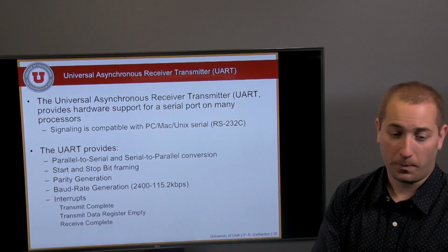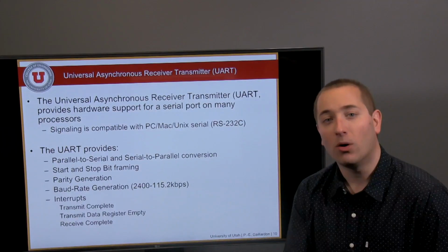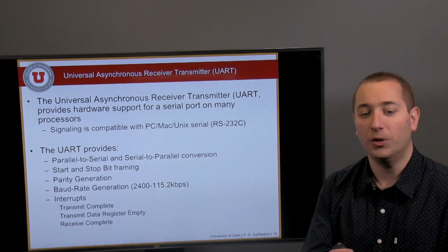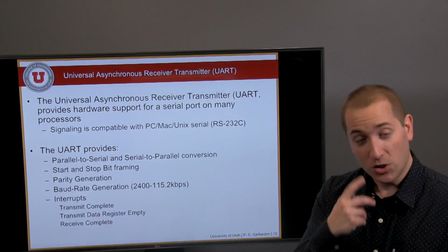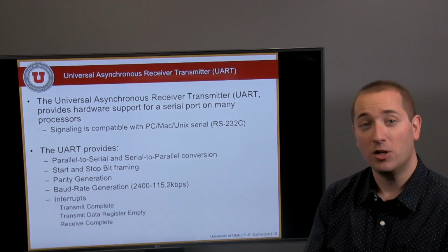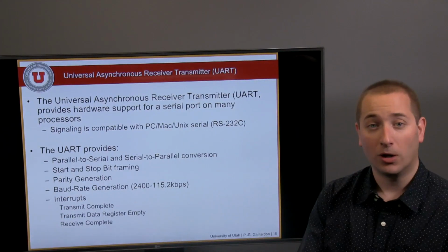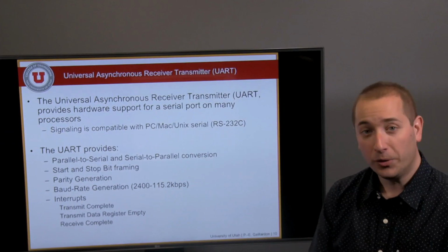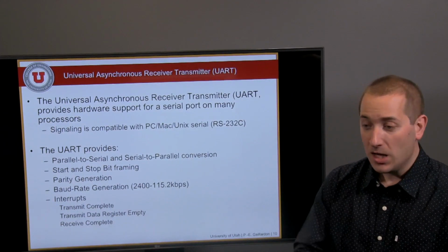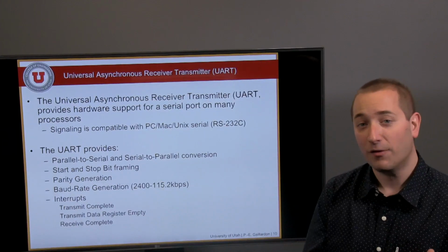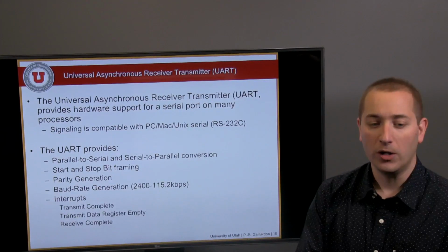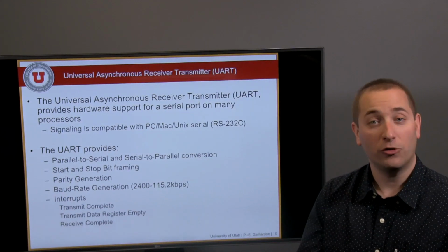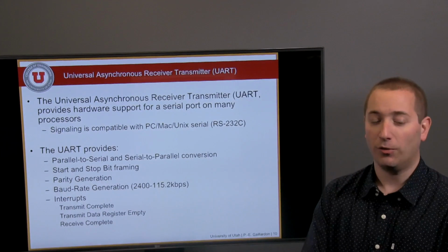Unix systems. The basic idea of a UART module is to provide parallel to serial and serial to parallel conversion. So you will basically provide your information in parallel as a bus to your UART, and the UART will take care of the serialization on the sender side and deserialization on the receiver side. It will also encapsulate this data frame with a start and a stop bit in order to be able to transfer the information and resynchronize on the receiver front.